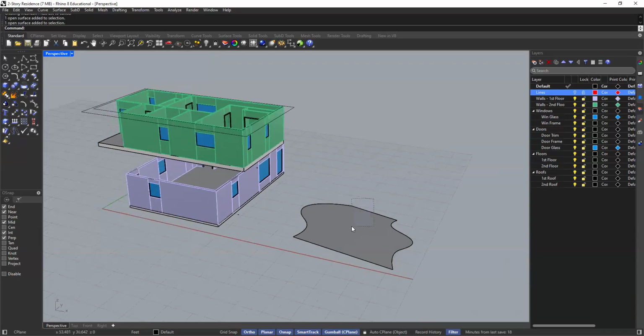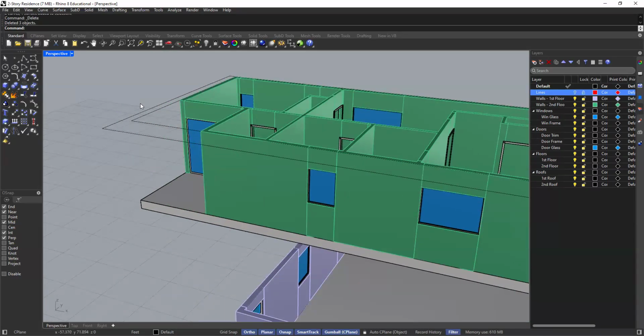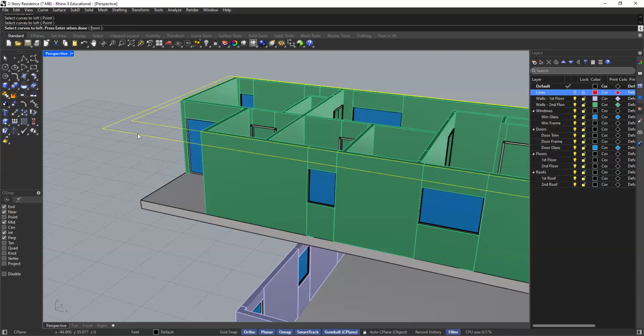So we're going to take that same principle, but apply it here to our angle. And so I'm going to type in loft. I'm going to click there and click there. So I want to create a surface between these two. Okay, it's asking which direction do you want kind of the sweep.